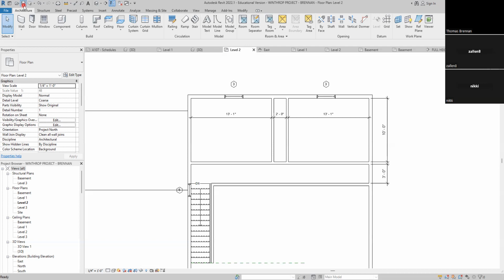Okay, now this wall right here, we can fix that. So just click on that little piece and delete it. Okay, good. So now those walls are good. Now, let's start the wall command and we'll do the 13-foot one on this one side. I tell you what, just pick a point and pull it up, and we'll place some temporary dimensions. Escape out of there, because you're still in the wall. Click on that and make it, you're pretty close. Click right on there and make it 13-foot. Making sense now? Very good.